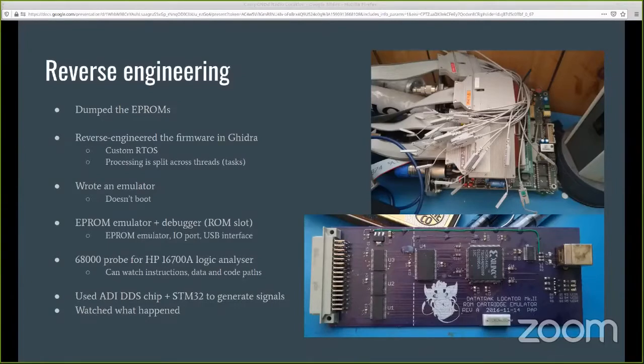So you can do cool things like telling the logic analyzer to record which addresses were executed, or which addresses opcode fetches happened from, store that, and import that into Ghidra to set code addresses and instruction references, which helps a lot with the reverse engineering.